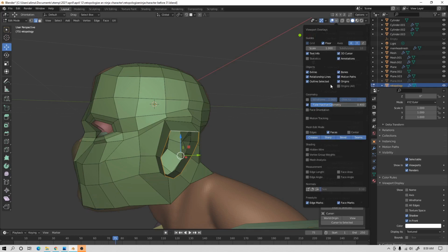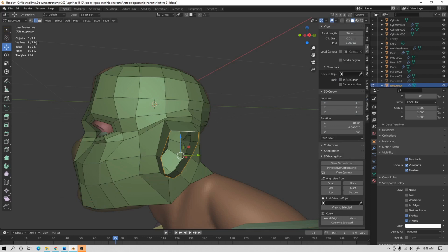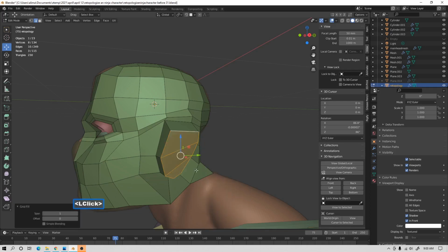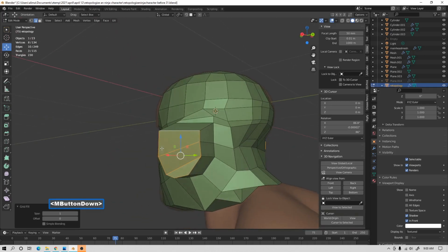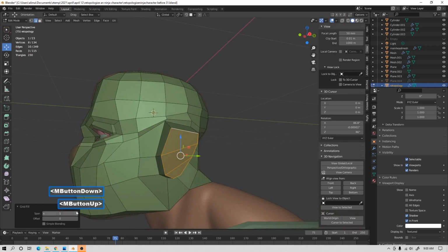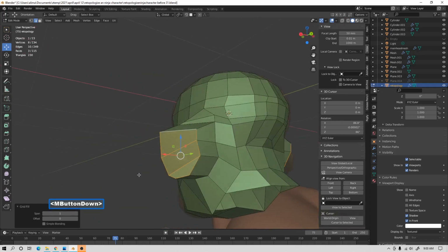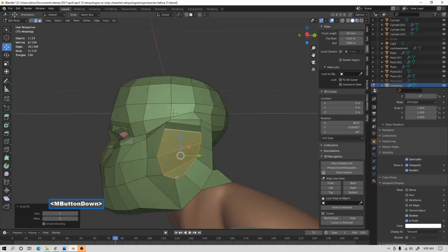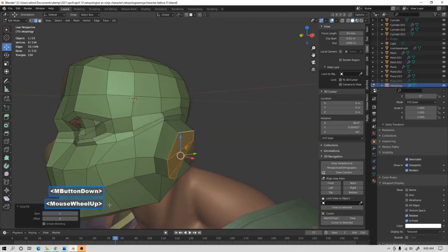I'm going to open Statistics now. So this is 8 vertices. When you have 8 vertices, you can use something to quickly fill in geometry called Grid Fill, which is nice. I'm going to hold Control and press F. This brings up our Faces menu. Then I'll select Grid Fill, and that is filled in. You can change how things are filled in here.